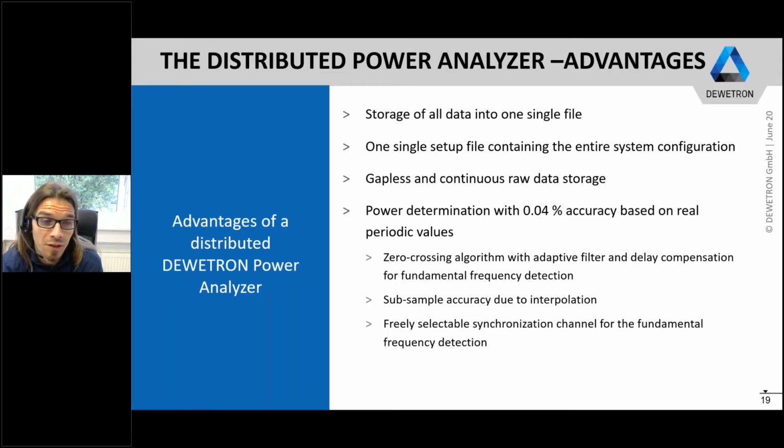And the synchronization source is freely selectable. So per default, it is the voltage channel of your first phase, but you can detect the fundamental frequency on any voltage channel of your system, or also on any current channel on your device under test. And the fundamental frequency is automatically detected in a range from 0.2 Hz to 200 kilohertz.